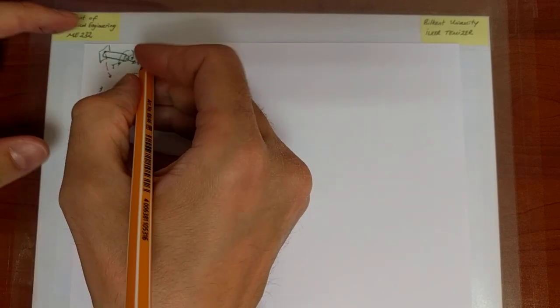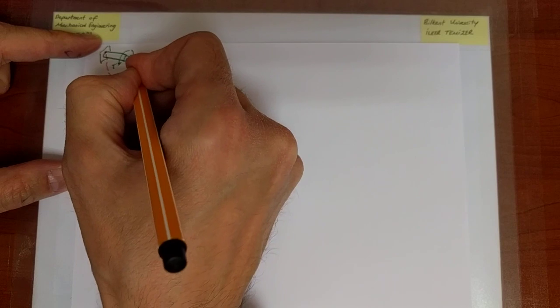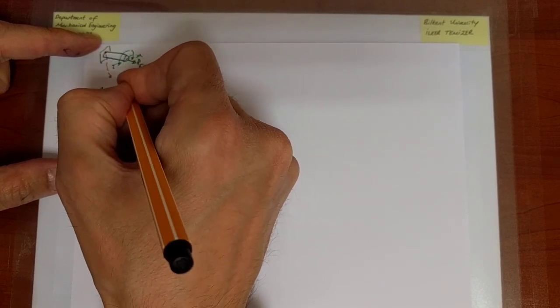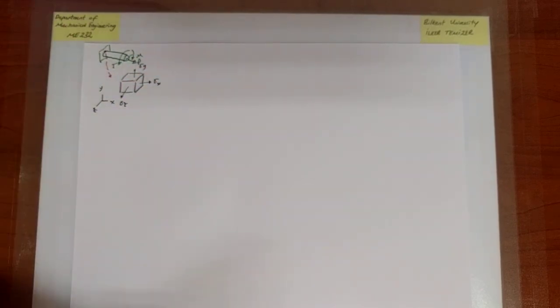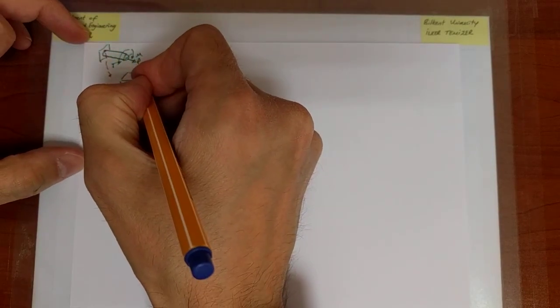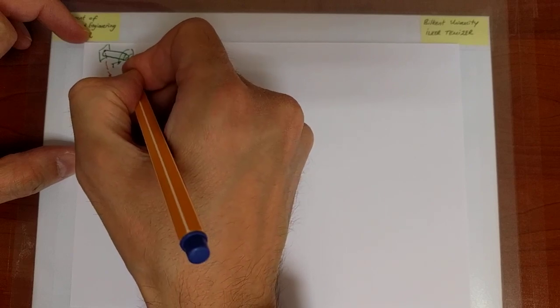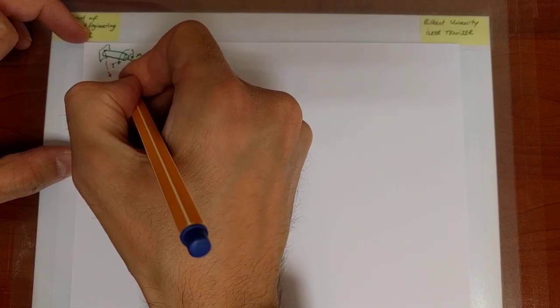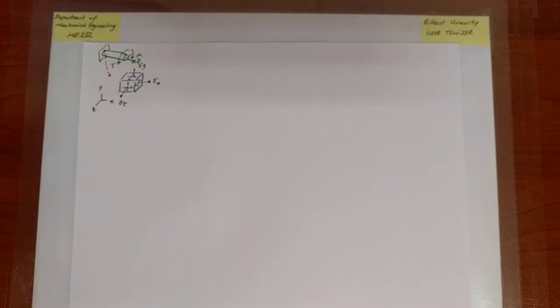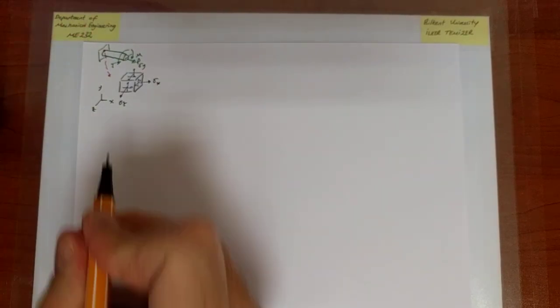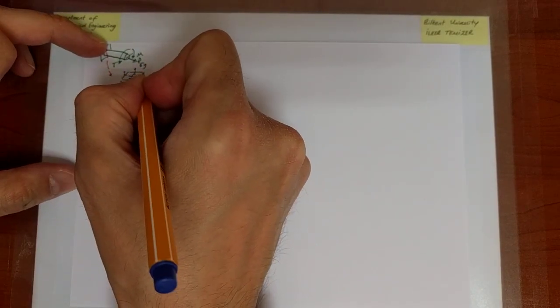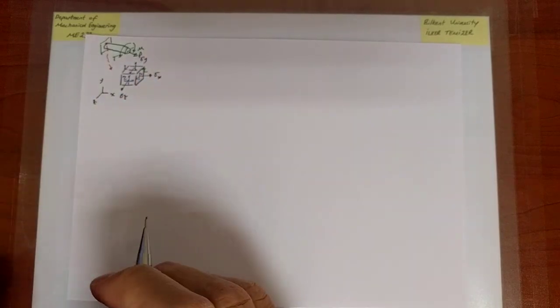So in general, there will be normal stresses, as well as shear stresses. So let me not write all the shear stresses presently. I'll just very quickly indicate them over here with these blue lines. So I have both normal and shear stresses. So I'll just write tau here. There will be 3 taus, well 6, but it's symmetric. So overall 6 independent stress components.